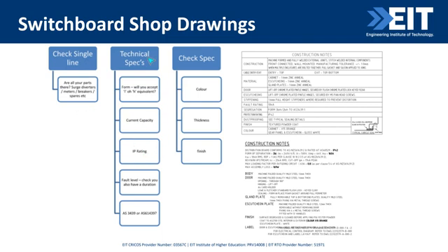You want to check your technical specs, which would be in that document. So our form, like we've spoken about, how much amps it can handle, what the IP rating is, what fault withstand level the board has, and which standard it's complying to. You could even then check things like the color or the thickness of metal or the finish of the metal to make sure it looks like how you want it to.